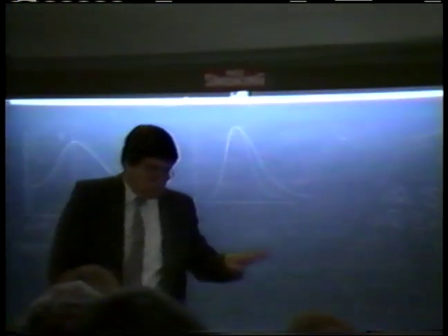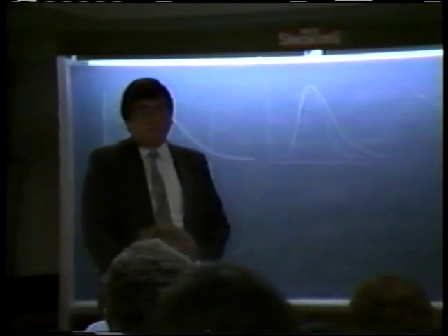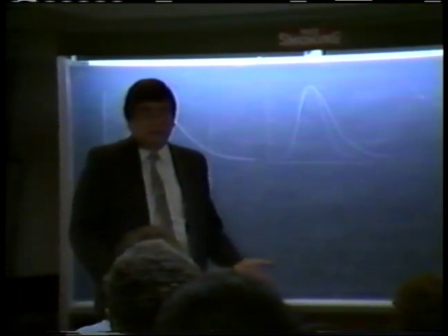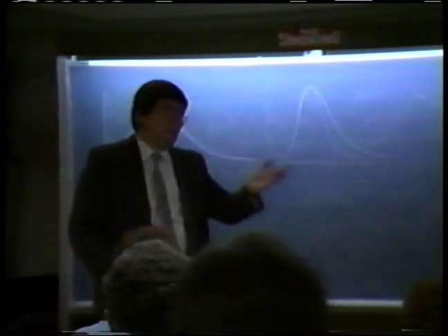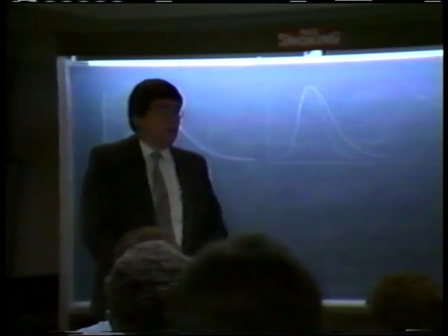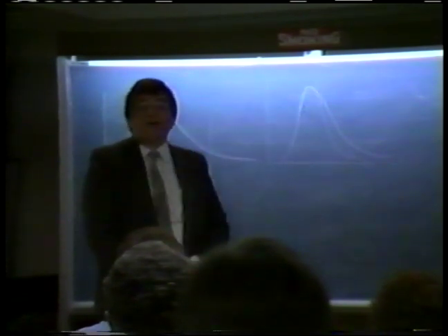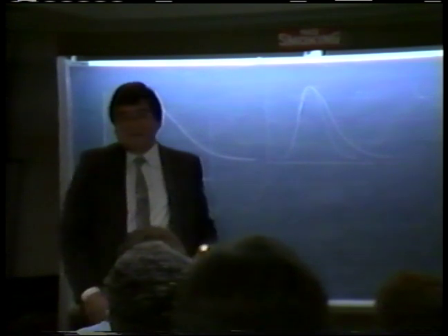It could be a kinematic wave. So if it could be a kinematic wave, let me first say that we are going to be pretty much leaving aside the concept of inertial wave, because we already said that it does not apply for our flood calculations, and we're mostly interested in floods. Perhaps some of you may be interested in the short waves. In fact, a lot of short wave calculations and theory has come out recently out of Delft and Danish hydraulics. They're already through with the flood a long time ago, and they're now looking at the short wave.